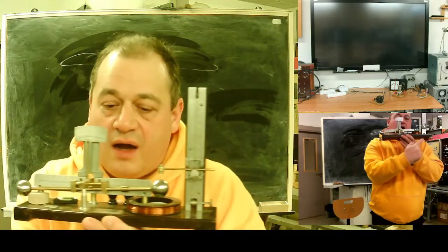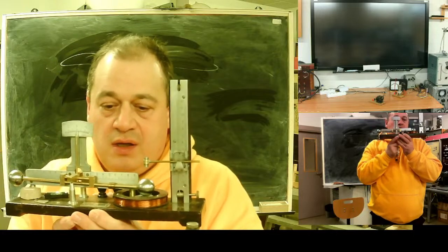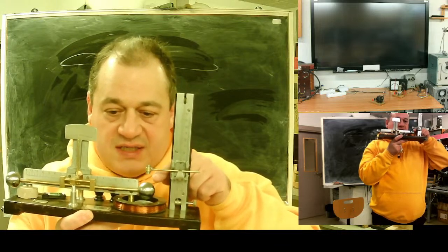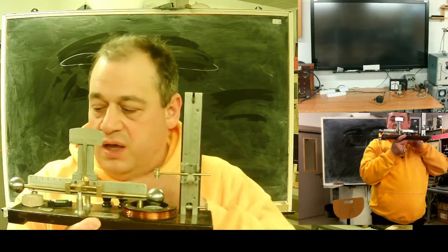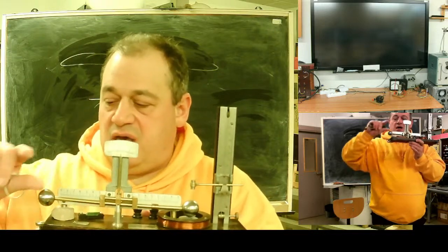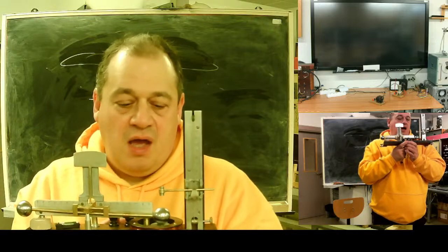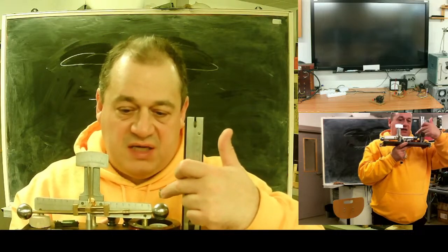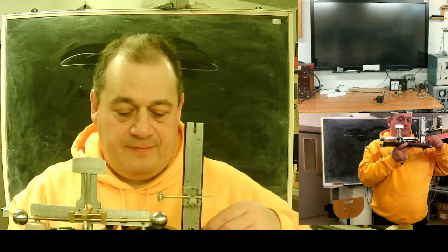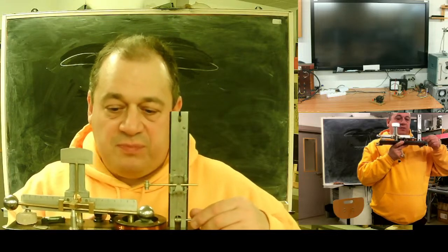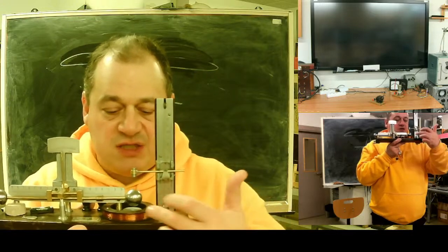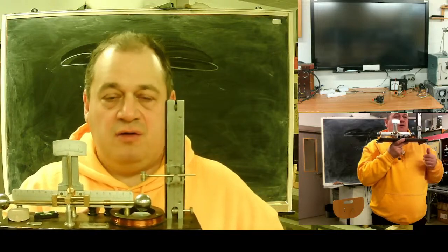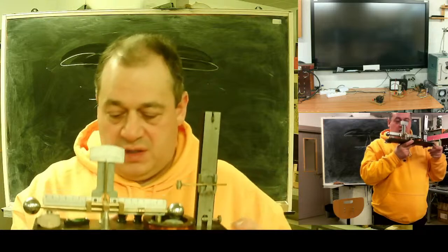So what's the idea? I have this current coil. If there is a current, this coil drags down this steel ball, and the whole balance tilts, and here should be a contact. How is the trip current adjusted? Here I have a magnet, and it creates an opposite force. This one is the operating force. This one is braking, works against operation. Here is my current balance.